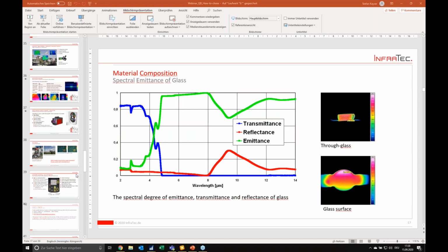Active thermography therefore can be done with a microbolometer as well as with a photon detector, but it's more likely to be done with a photon detector because you can synchronize these detectors better. The base performance is better in terms of thermal sensitivity, but also for the microseconds and the shorter integration times and the snapshot behavior.